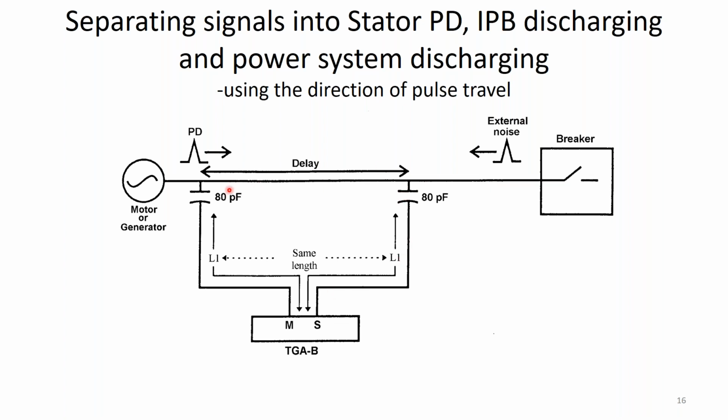And of course that pulse will arrive at the system sensor input 15 nanoseconds before it reaches the M input. So S goes digitally high before M goes high. And we have an electronic decoder that says, hey, if that pulse took 15 nanoseconds delay, that pulse must have come from the system. And of course, if we have any arcing and sparking, broken insulators or poor electrical contacts, the flexible links on your isolated phase bus or your output bus, they are going to get there less than 15 nanoseconds apart.